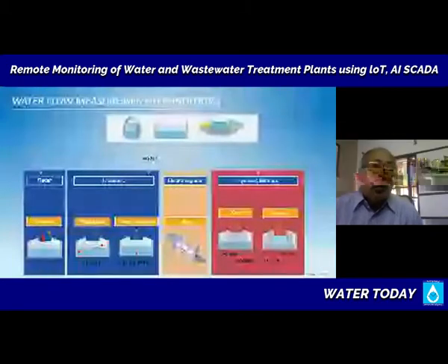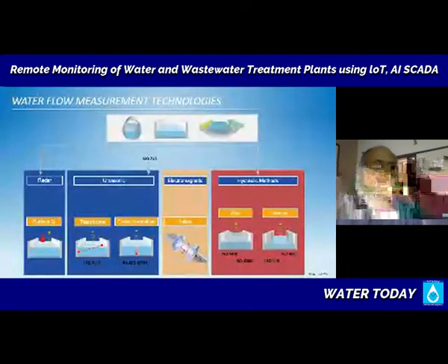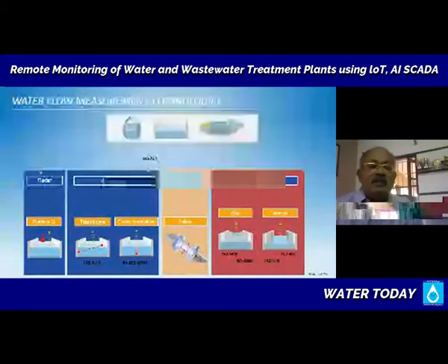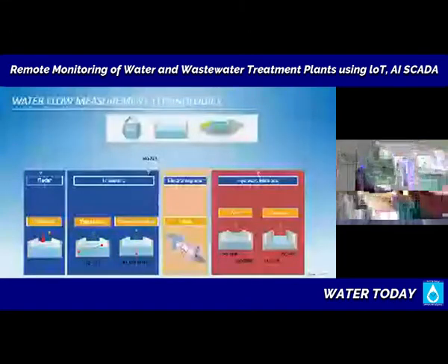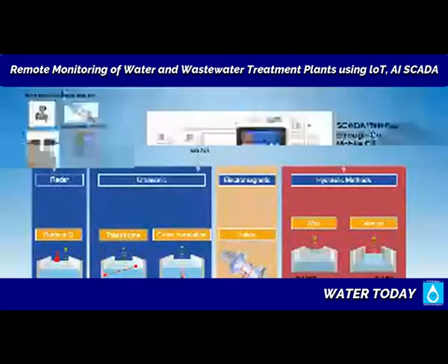Yeah, we've been looking at the sensor technology in terms of ultrasonics, and in this slide you are seeing what are the options you are having. Now, here you need to consider your situation. Am I in a pipe which I can cut and put a meter that can go inline? So I get a very economical, for example, Woltmann type or a mechanical water meter that I can put inline. That is one option. Am I able to isolate the flow, cut it, or drill the pipe to put a sensor? If the answer is no, then you may have to put a sensor that does not intervene into the pipeline. That is the second one that you see, which is a clamp-on sensor.